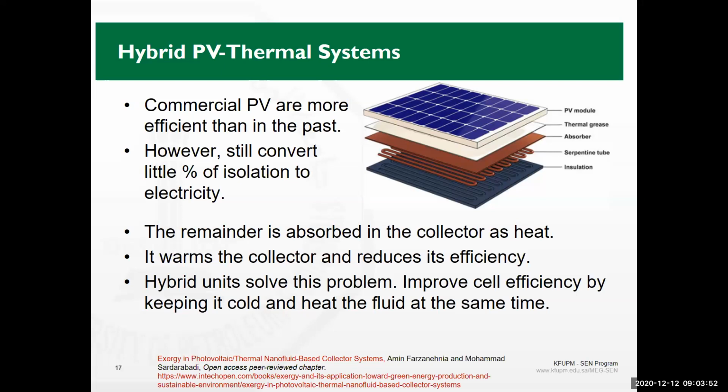The problem with the panels is that their efficiency reduces when the temperature increases. So there has been research for more than 10 years to effectively cool the panels, and people used lots of things. Some used tubes passing on the back of the PV panel so that they can absorb the energy and keep the panels cold. People, especially a group in our university, have started to use some sort of jet cooling, where they have water sprayed on the back surface of the panel, and spraying would have a high heat transfer coefficient, so it does effective cooling,